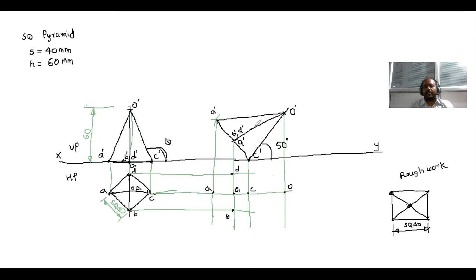Now, which lines are dark, which lines are dotted? To see that, we are looking from the top side. Always remember that opposite of the side where we draw the drawing, we look. Since we are now drawing in the top view, we should look from the opposite side. So this arrow is the direction of observation.